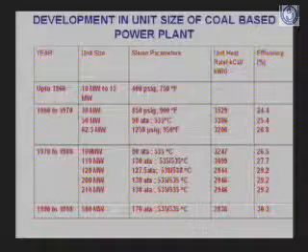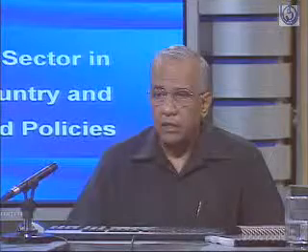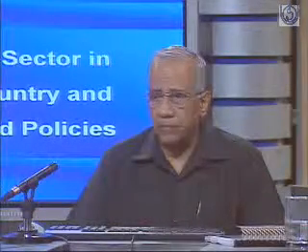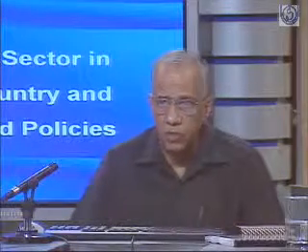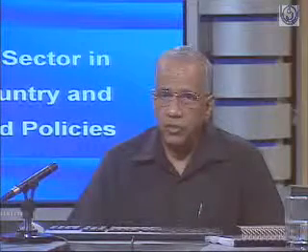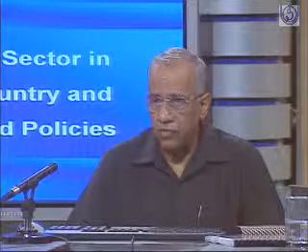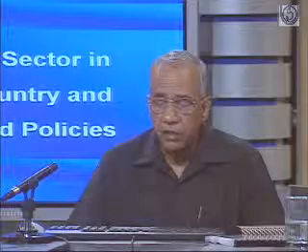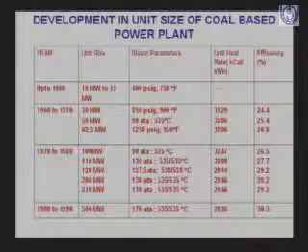But then it has something to do with the size of the machine as well. If the size of the machine goes on increasing, the blade heights of the machine get larger. I will show you the cross section of the machine, how it looks, and then you can appreciate that when the blade height is more, you can machine it better, you can give it the better curvature required, and a smooth finish can also be given. Therefore marginally, efficiency also depends on the unit size increasing.